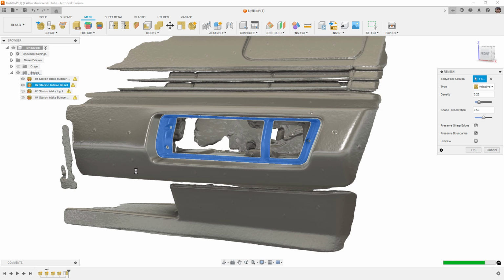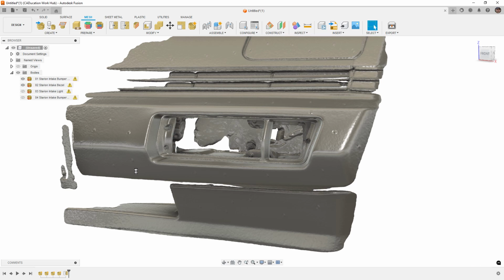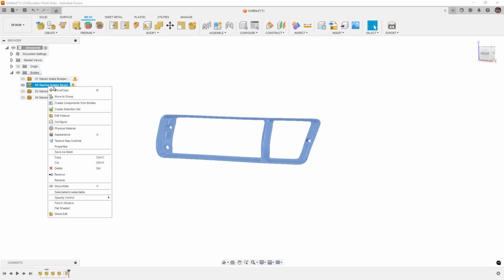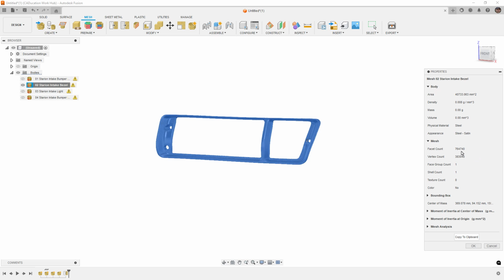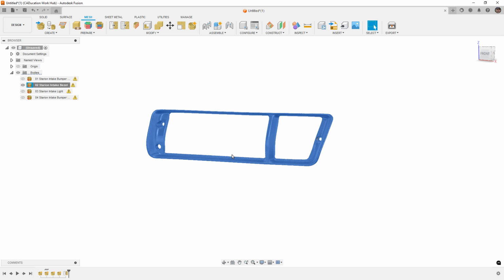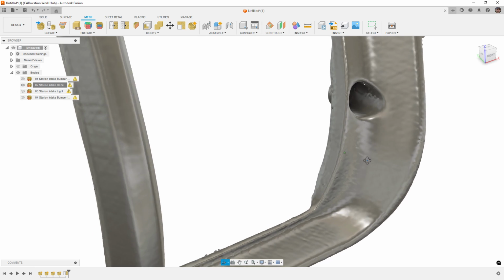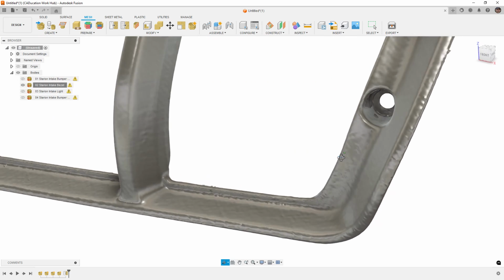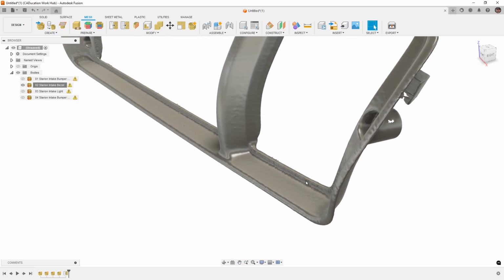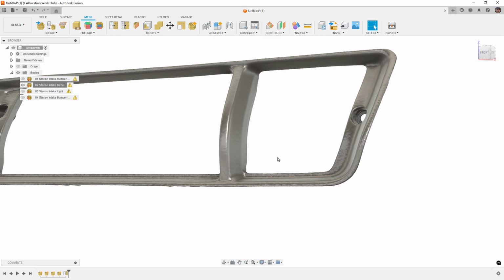With a 3D print, we have a little bit of flexibility. Obviously, we can make a part, try it out, see if it fits, and make some adjustments from there. But we've captured the remesh, and if we take a look at the properties and see how many triangles we got down to, we went from about 2 million, it was 1,999,000, to 764,000. So quite a bit lighter on the mesh side of things. Looks like we still have enough detail for what we need. We've got the mounting hole locations. Some of the edges may be a bit rougher, but overall I think it looks okay.